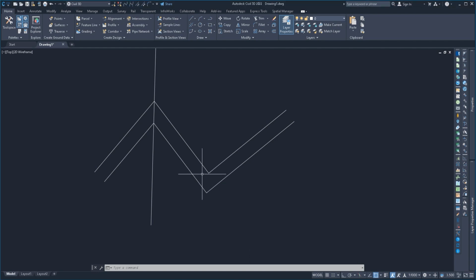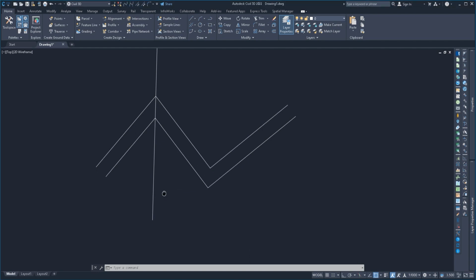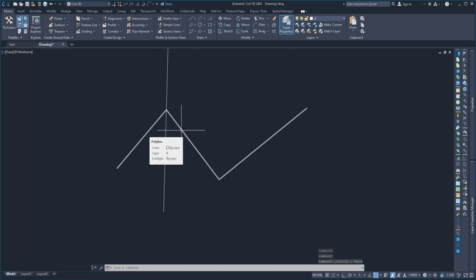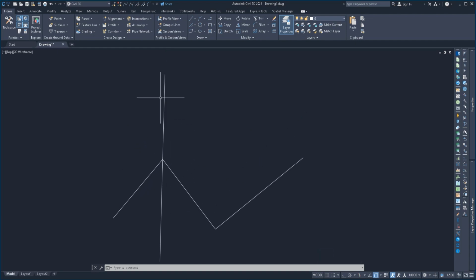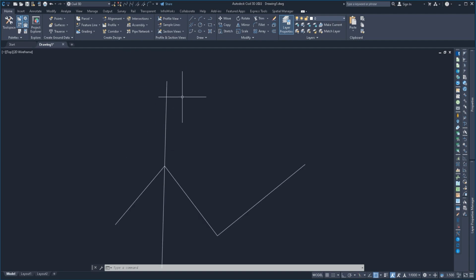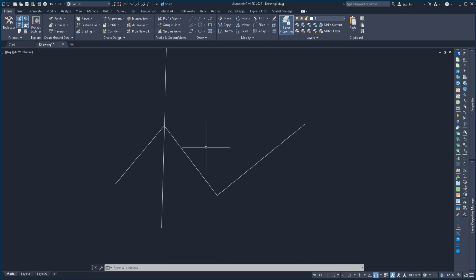Now we can use this to our advantage inside of Google Earth, or even if we are drawing the keyline pattern using just hand drawing tools. One of the things that the trajectory enables us to do is to predict how our geometry is going to look upslope or downslope from our guideline. For example, if our slope is looking a certain way up here, then we're going to know in advance how our pattern is going to look like relative to that slope. So if it's not going to work, then we don't have to actually spend time to offset the pattern first before we can understand that it's not going to work. We can make changes in advance, and in this way we can save a lot of time.